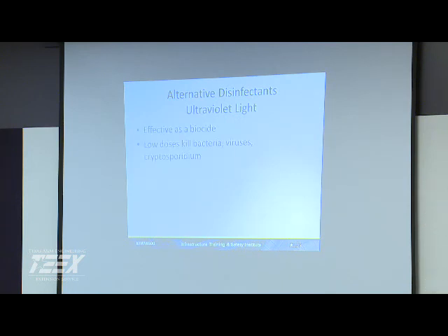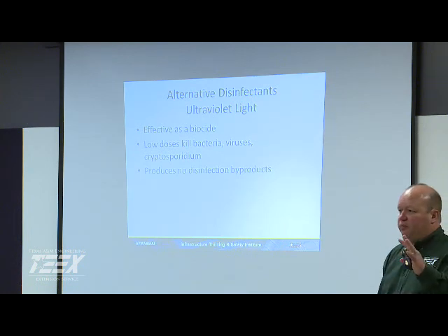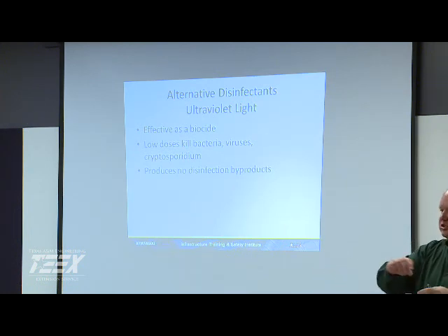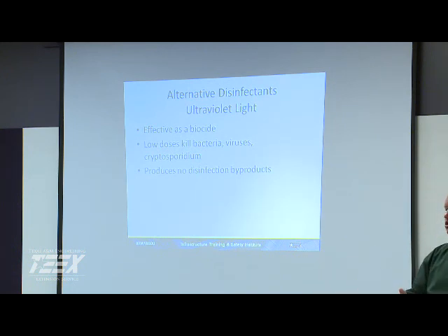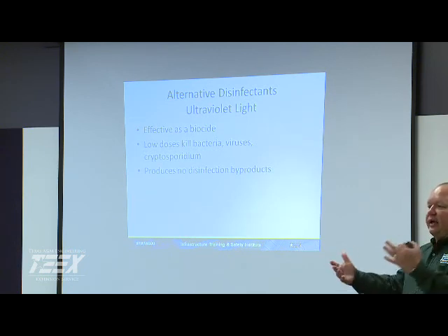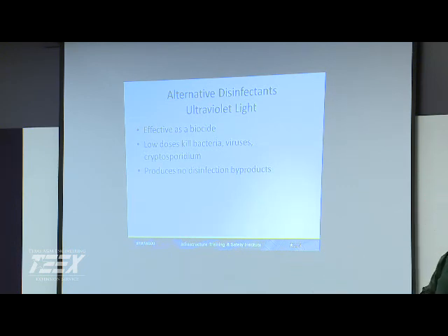UV is beneficial. I'm surprised how much they were using it in the Virgin Islands. It's like they just see the little light in there, and I guess it gave them that warm fuzzy feeling of, the light's glowing, but what's your penetration, what's your turbidity, what's your effectiveness of it, and if you don't have a residual, how do you have confidence that water's been treated properly, other than you pull a bacti test and you find out 5 to 10 days later that it wasn't. So we're required to have residuals.